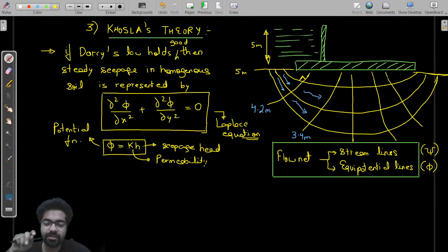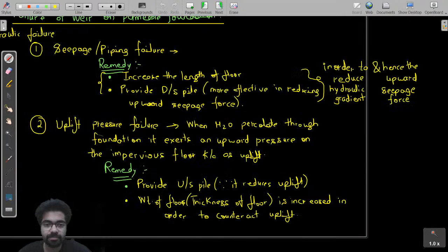Sushma, in Lacey's design, you must have solved the equations for width and depth simultaneously. That was the final regime dimensions, obviously, when everything becomes constant: discharge, silt grade, everything. Then Malaya is asking, sir, why is the crest level lower than that of the weir? Malaya, listen very carefully, because of the silt.